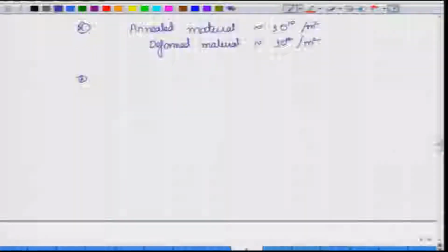Now, there are dislocations inside it, and if a very small amount of stress is acting on a single crystal, the dislocations would be moving on only one set of parallel planes, and that is something that we discussed when we talked about critical resolved shear stress. Let us say you have different sets of slip planes inside a single crystal and you are applying stress. The one which reaches the critical resolved shear stress first will start to have dislocation glide on it first and foremost.